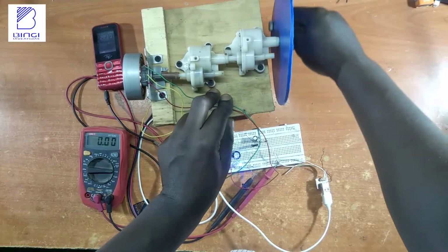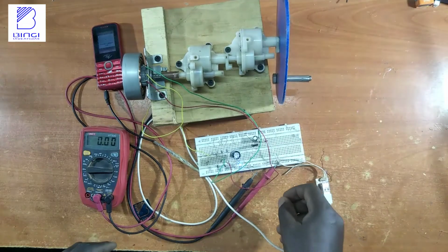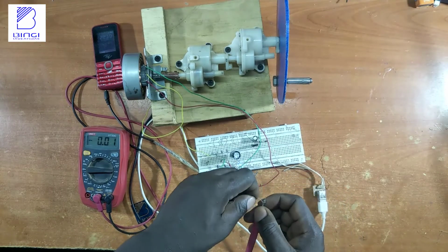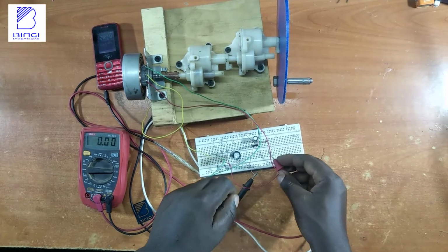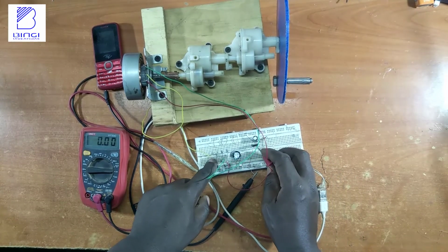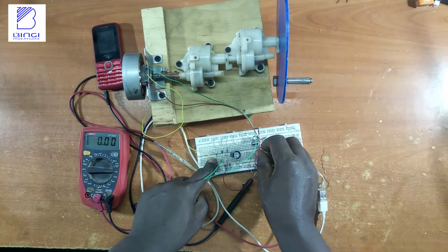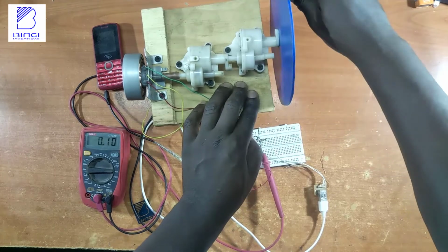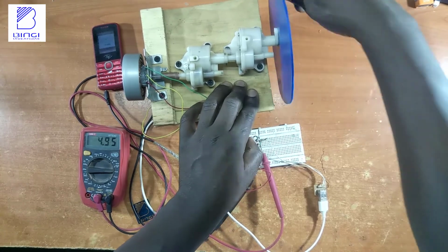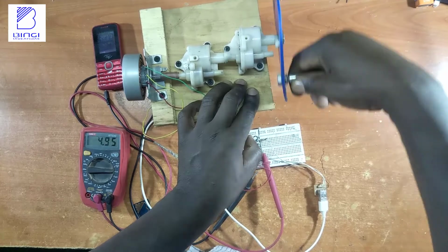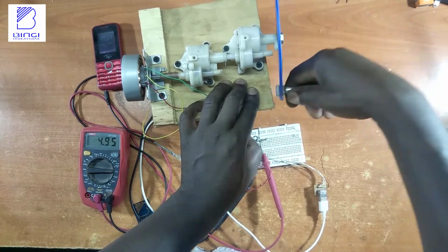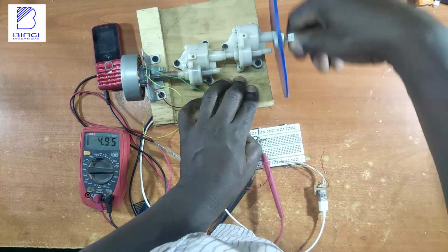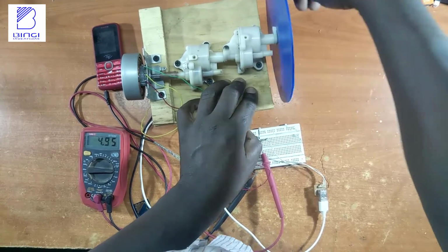Now, I connect a multimeter to indicate how much voltage is reaching the phone for charging, and when I start rotating the generator, you notice that the voltage does not exceed 5 volts. Of course it's 4.95, which you can approximate to 5 volts. However much I increase the speed of the generator, the output voltage reaching the phone remains the same and does not change that much.